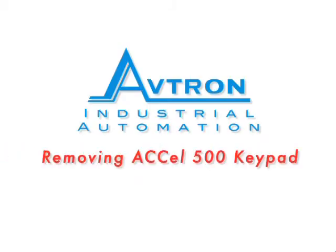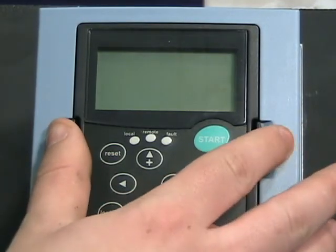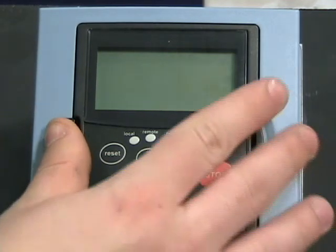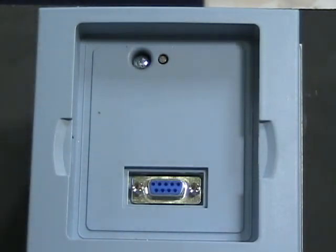Removing the ACCel500 keypad. Push in the tabs on the side with your thumb and finger, and pull the keypad outward. Removing the keypad will reveal a serial input, which can be used for communication with your computer for maintenance. A special cable is not required for communication. A standard 9-pin serial cable can be used.